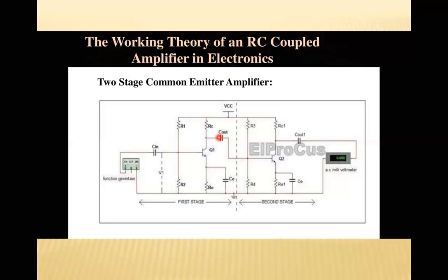When a second stage is made to follow the first stage, the effective load resistance of the first stage is reduced due to the shunting effect of the input resistance of the second stage. This reduces the gain of the stage which is loaded by the next stage. In a three-stage amplifier, the gain of the first and second stages will be reduced due to the loading effect of the next stage. However, the gain of the third stage has no loading effect of a subsequent stage, because the third is the final one.